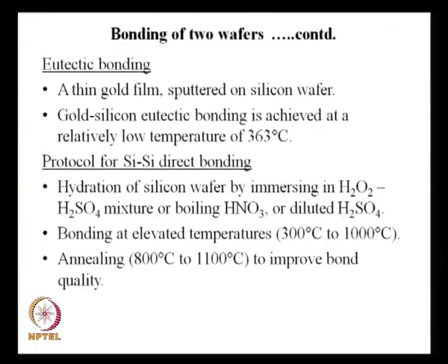This eutectic mixture has its unique properties. Gold and silicon form a eutectic mixture, and if it becomes a single phase, then basically the bonding is practically a single material. So it is like any direct bonding if it forms a single phase.